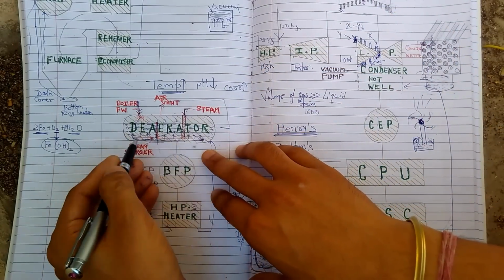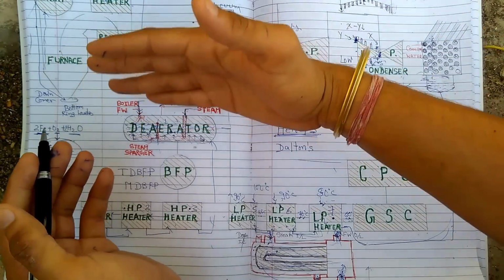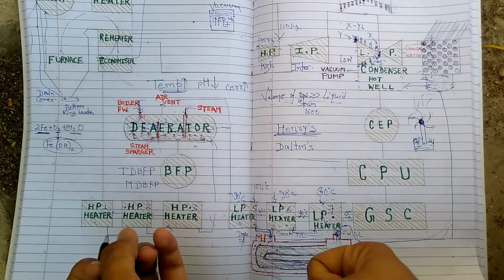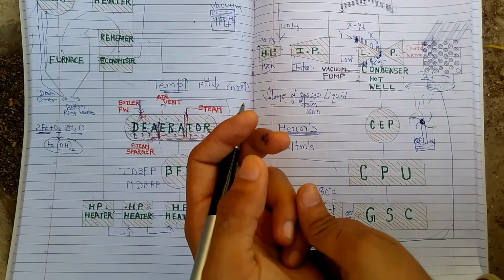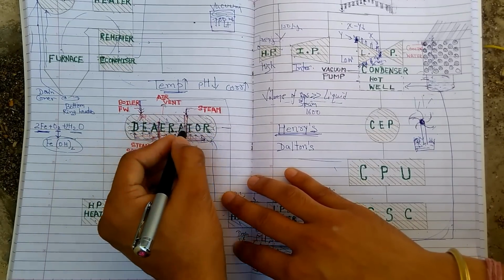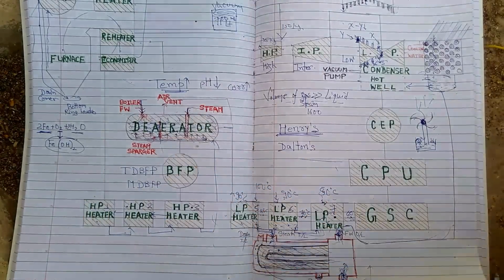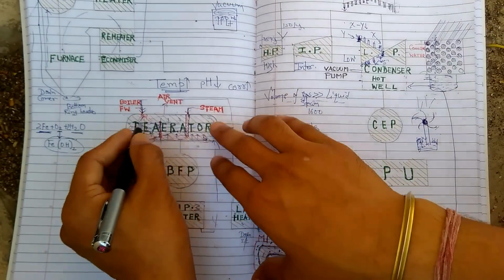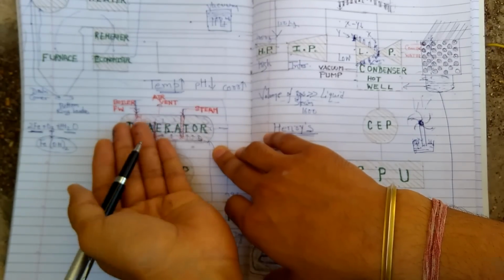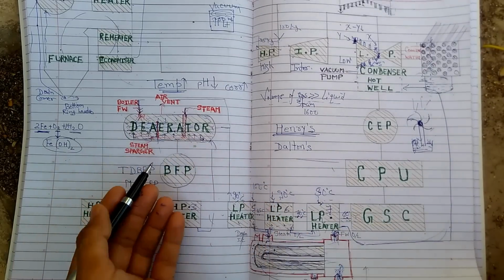So if I heat up this water, I need to apply more force to keep it in the liquid state. That is, my vapor pressure will increase. Okay, but my oxygen and CO2 will get out of it due to the reduction in partial pressure. Also, if I reduce the pressure of the outer atmosphere in the deaerator, I can again move the oxygen and CO2 out of this liquid. So if I am increasing the temperature of this liquid, my oxygen and CO2 are getting out of it, and then I have an air vent here, and those get out through this air vent. So I have deaerated water after this deaerator.